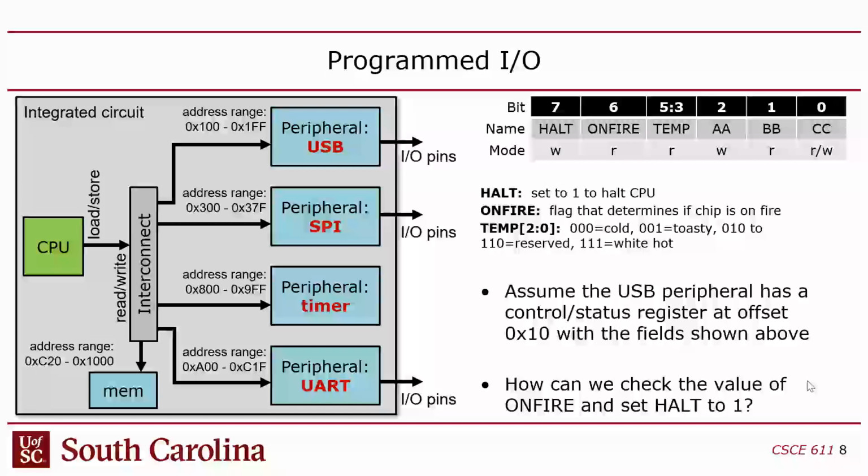Okay, so all right. The other thing you have to understand is that the sizes of these control and status registers are going to match whatever the native bit width of the processor is. When we were using the Atmel 328P, I think it's 328P, that was an 8-bit processor. So all the loads and stores were 8 bits, and thus all the control and status registers were also 8 bits. On the ESP32, obviously they're 32, hence the name. They're all 32 bits. In this example, I'm showing an 8-bit one because this is a leftover example from when we were using the Atmel chip.